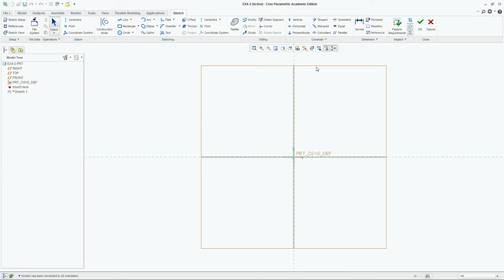Then I'll come back over here and click on my Sketch View button. Now, with this object being a round object, that means that I am going to have a center line in my object. There's two different center lines that I have the ability to use. There's the 2-point construction center line, and then there is a 2-point geometry center line. I'm going to use the 2-point geometry center line for this. And I'm just going to click in the center and then move straight down. What that does is that creates a center line that goes up and down, on forever and ever.